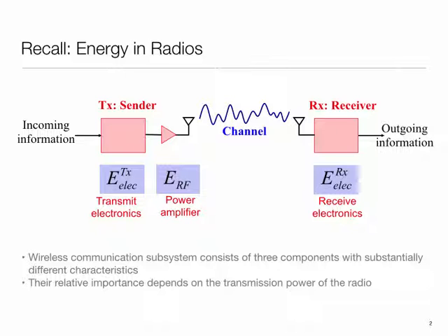So for short range radios, in the extreme, what may end up happening is that the receiver dominates, just because the receiver electronics generally tends to be more complicated. What this has resulted in, in recent years, like the last decade or so, is revisiting some of the ways radios were power managed. If you look at the pre-short range radio era, radio management was basically a matter of managing the RF power. And the best trick that we knew was to play with the rate at which we are sending.